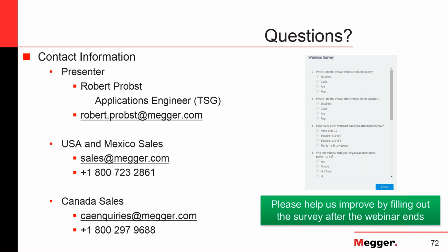This is all fairly complex stuff, typically not handled via primary injection because of the complexity of the slope test, harmonic restraint test, and through fault test. Those are typically handled via relay protection schemes. So yes, as Robert said, it can be done, but it can get costly and sometimes beyond the capabilities of primary injection systems. Thus, relay protection schemes and relay test sets are used to validate those particular elements.